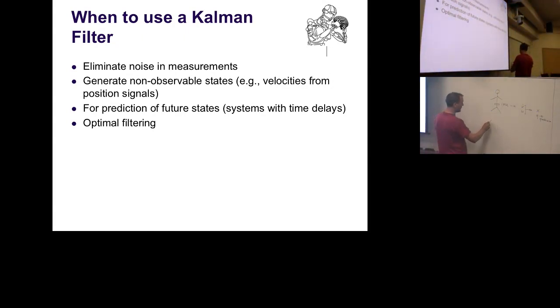I showed you this a long time ago when we did Laplace transforms. If you do x dot equals alpha times, let's call this a measurement here, y minus x. So y is now a noisy measurement of x. Well, if I put y in here and let it run and develop, then x becomes a filtered version of y. It's a crummy filter, but it works.